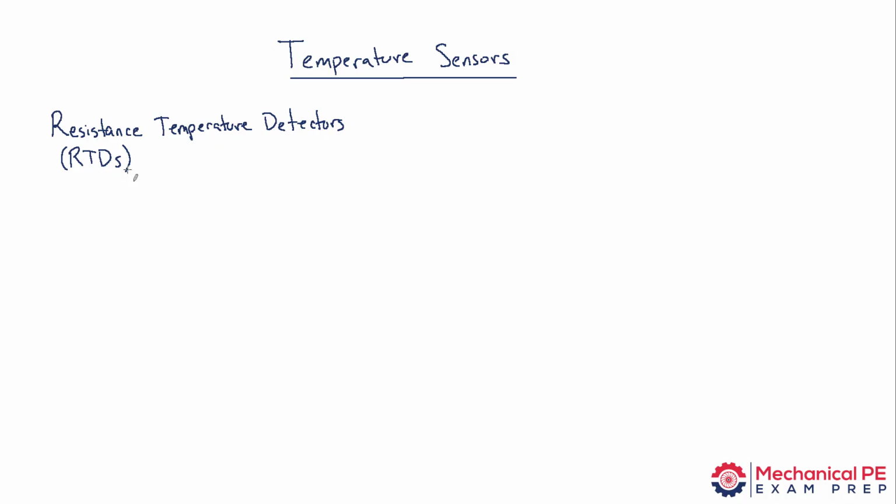These are probably the simplest of the 3 types in terms of the analysis, because the relationship between the resistance measured and the change in temperature is linear. Now, strictly speaking, that may not be true because there's a second constant. There are 2 constants of thermal resistance, alpha and beta, but beta is often ignored, and that is the guidance in the reference handbook as well.